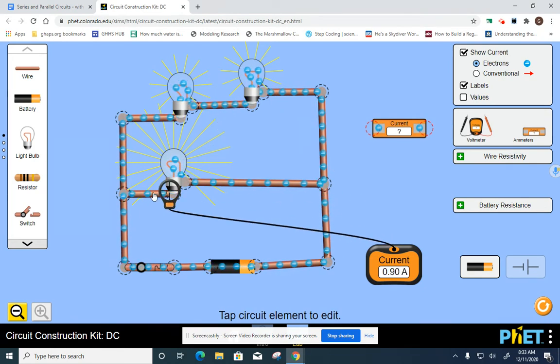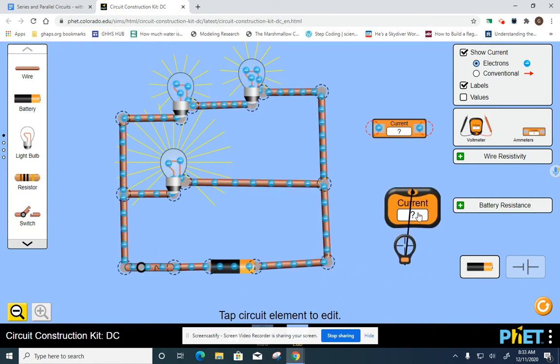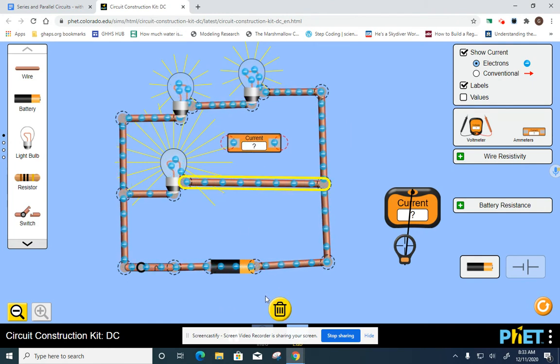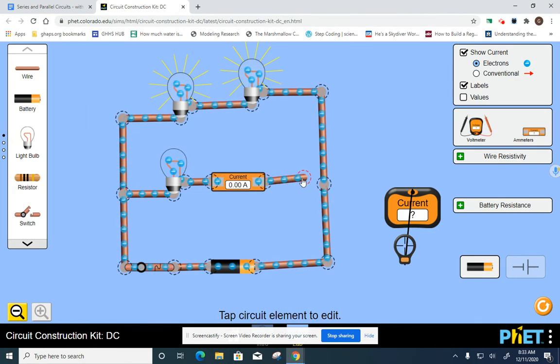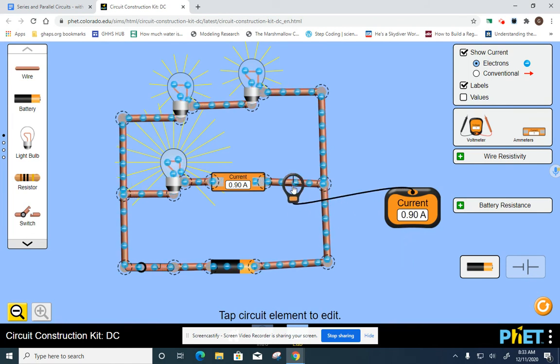So we can measure the current anywhere that we like. Now, this is a non-invasive kind of measurement. If I want to use this other kind of ammeter, I actually have to insert this one into that circuit. So what I'm going to do is insert it like so. And now I need to have that charge actually flow through that device, and then I can measure that current using this. So I can get that value in either way.